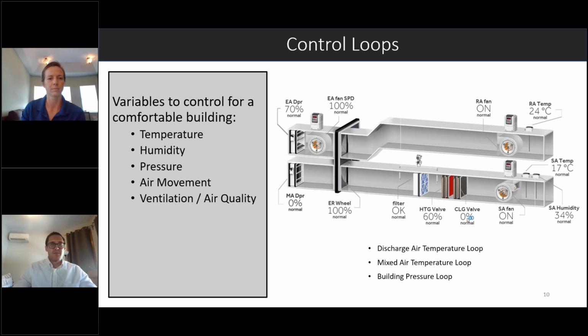You put it at a set point, maybe you say, if you see this much CFM or this pressure amount, that's going to signify that there is airflow. Whereas an airflow sensor is telling you the exact reading of it. So you're going to say, okay, I have 800 CFM flowing through that airflow sensor. So it's going to give you the exact amount.